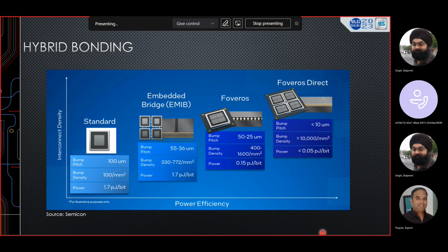Now, you would carry the silicon from one fab to the other fab and then create a sandwich. So it's process and operation wise difficult to coordinate. There is some logistic extra cost involved because these two need to be perfectly synchronized. On the other hand, with the microbump technology, which is an assembly line process, in the two fab lines you create two dies up to microbump. You send them to an assembly line, a package house, and they just create a sandwich.